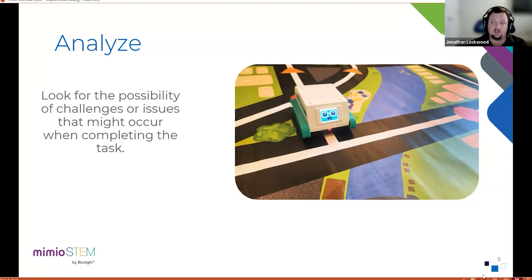within that line, right? So in the case of this picture here, we might want that robot to follow that white line. And on the bottom of our MyBot, we have a color sensor. So we want that sensor to adjust the direction the robot travels if it starts to read something other than white. So if it gets into the black area, it's going to correct the course of the robot to stay within that line as it's following.